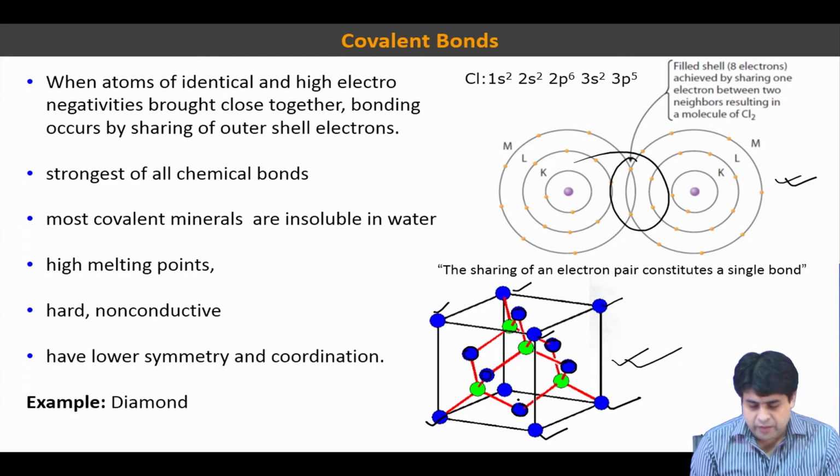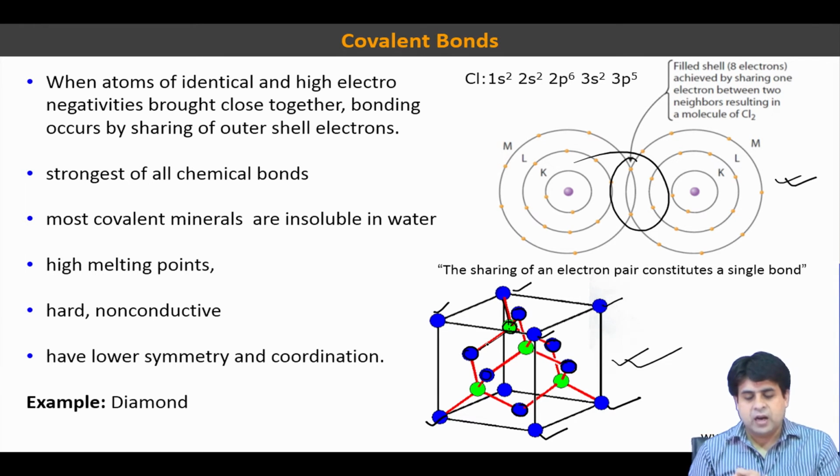Then you have 4 more atoms placed inside the unit cell, denoted by the green color, and they make this tetrahedral coordination. This particular carbon atom is connected with the face centered cubic atoms and the simple cubic atoms at the corner, so it is connected with 4 different carbon atoms.